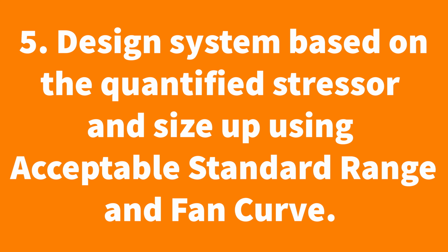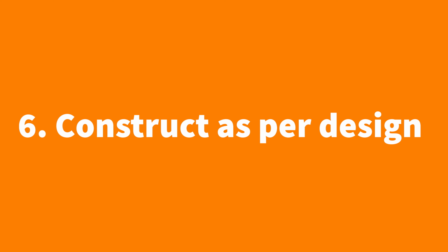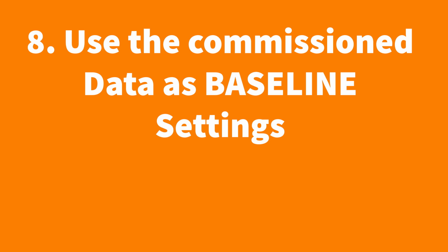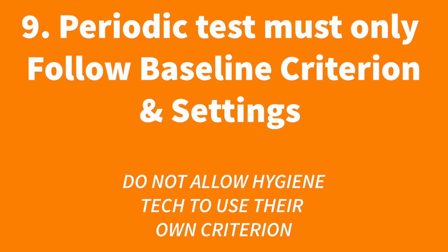So I have processes in that particular room. During the initial stage, when I want to do the general ventilation, I realize there are processes. I have a fume hood, for instance, or a plating tank, or a grinding process. I decide I'm not going to start with general ventilation yet. I'm going to locally capture this airborne contaminant. I'm going to locally capture the fume being generated by the welding process. I'm going to locally capture the grinding particulate matter, which is being suspended at high velocity, by using a local exhaust ventilation system.